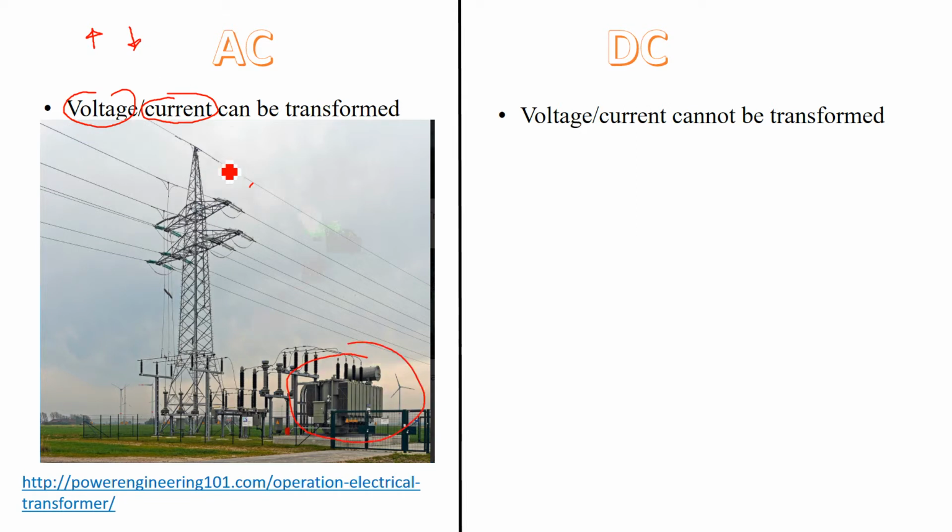So the high power lines that we do have, let's say that they are transmitting the electricity at a very high voltage, 20,000 volts. Now remember, when this electricity comes into your house, like I mentioned, it actually comes in on two wires, each one carrying 110 volts. So what you need to do is be able to change the voltage, take it from a very high voltage and bring it down to a much lower voltage. So this is what we call a step down transformer. And again, I have another lesson which is dealing strictly with transformers.